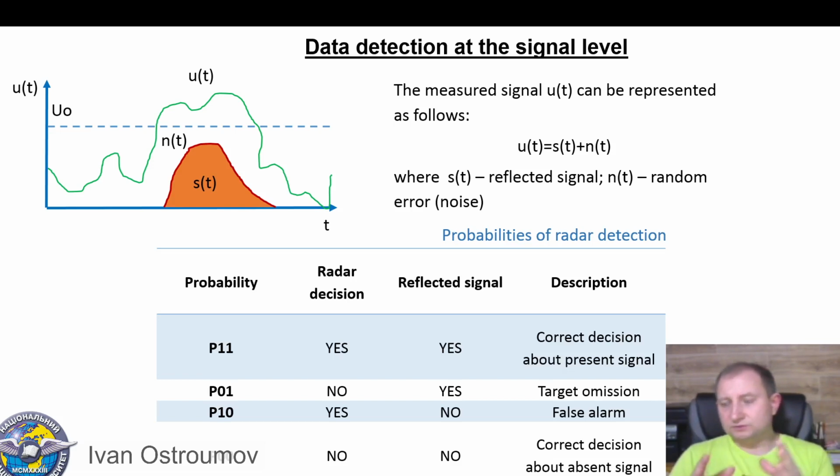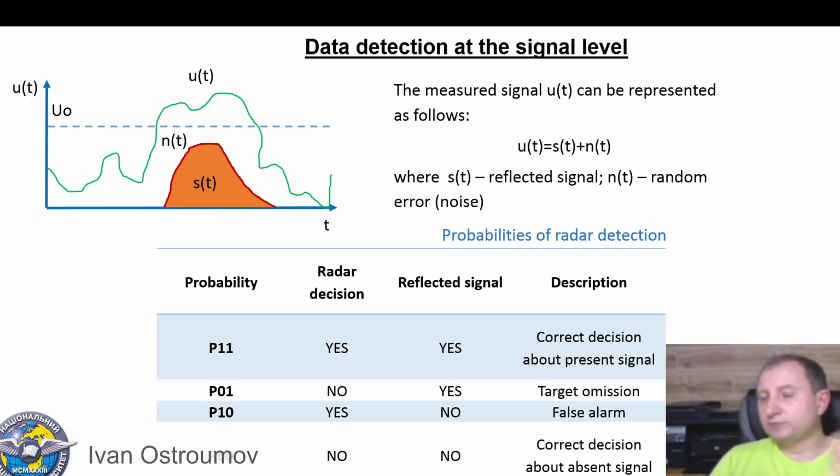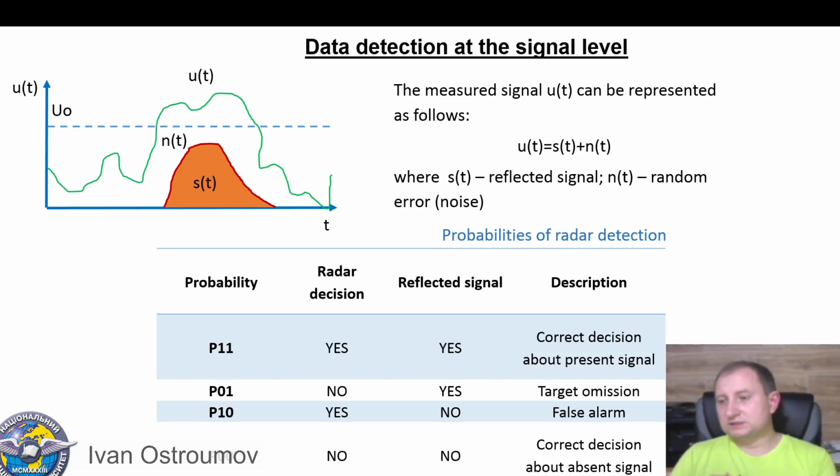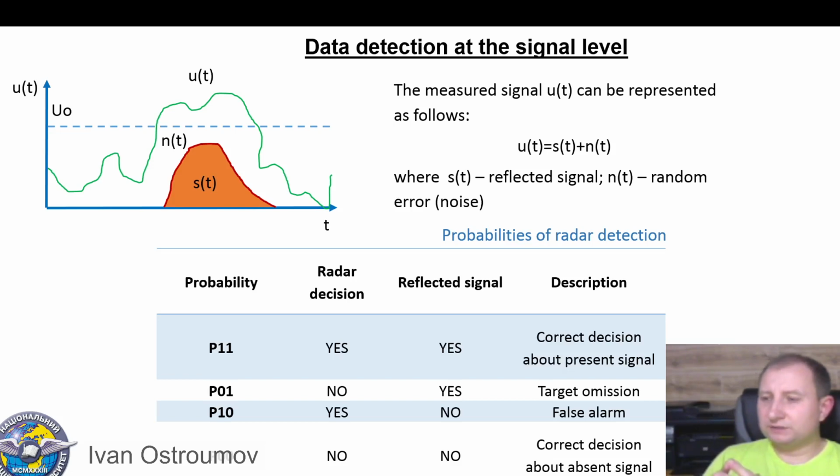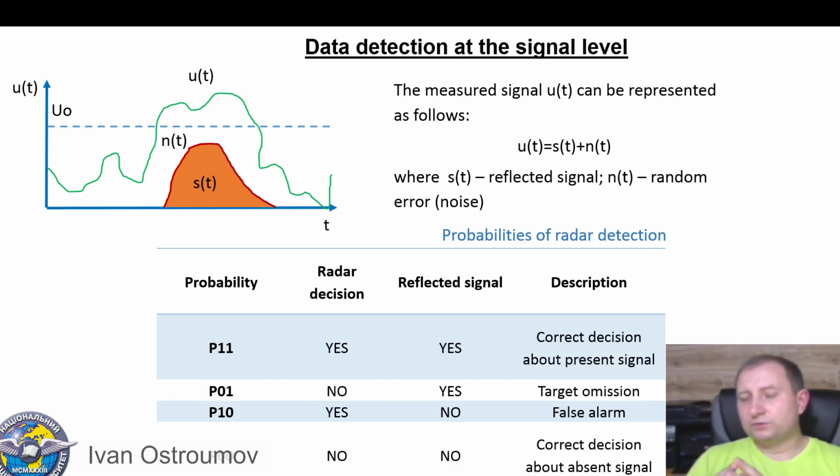Based on that, radar can measure the distance to the object by time of traveling signal in space to the object and return to the radar, and by direction characteristics of antenna system, because we know current direction of antenna system, and mechanically we can route this antenna location to the computer-based system to get precise coordinates of detected object.